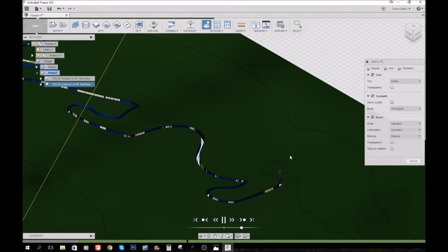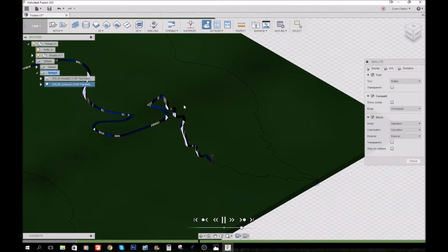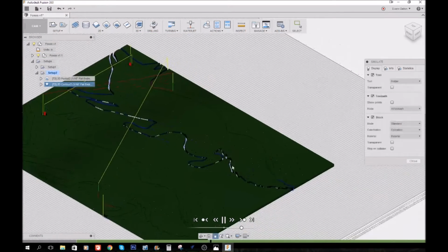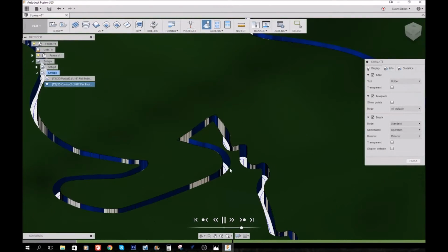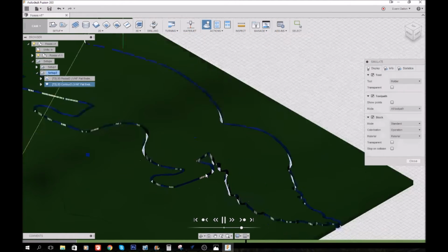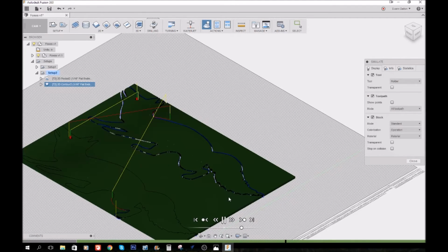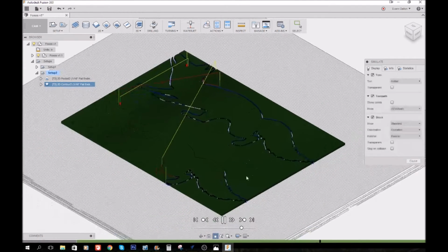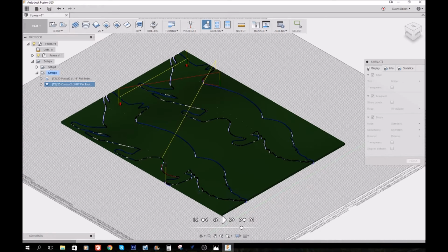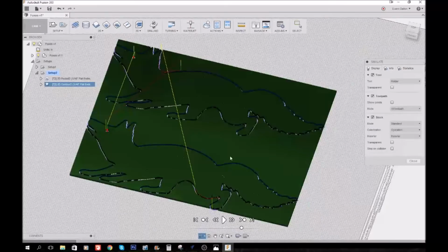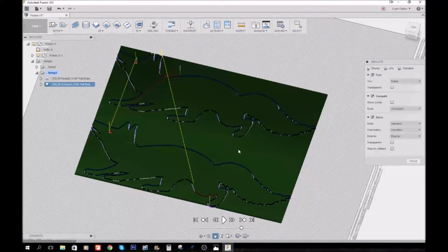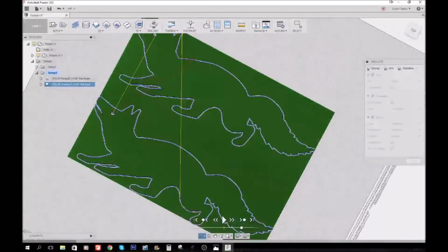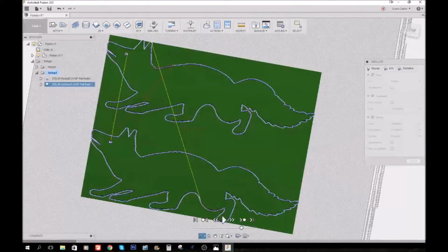But what we want is one continuous tool path all the way around the contour. If you put in an 1/8 inch end mill, you're not going to get a continuous tool path. It's going to stop right here and not cut any of this. So if we run an 1/8 inch tool around here, it's just going to smooth out these lines a little bit. No big deal. It's fine for this, especially since we've already specified to the customer that that's what we're going to do. So always make sure and clear it with your customer, because if you show them an image, it better look like that image when they receive it in the mail, if you want to get any sort of good review. So that's what our finished cutout looks like.